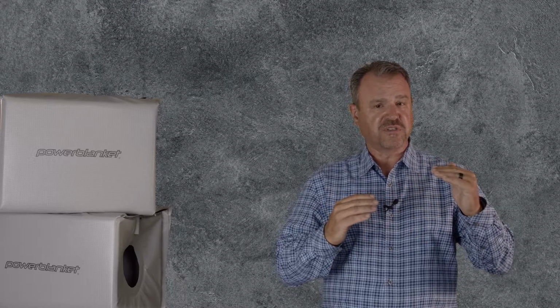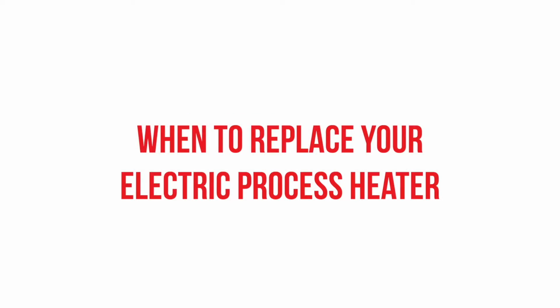When you're designing a process heater, we need to know the process ranges. What pressures are there? What temperatures need to be gotten to? What are the bad temperatures and what are the good temperatures? Overall, what can you tell us about your process so we can know for sure that we designed the right heater for the right application?